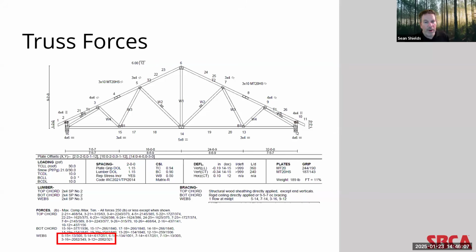As a reminder from part 1 of this presentation, trusses are designed as essentially two-dimensional structural framing elements. Their ability to resist loads is maximized within the plane of the truss, from the top chords down through the bearing locations. However, when you introduce compression forces like these, the truss designer needs to bring in the three-dimensional nature of the roof or floor system.